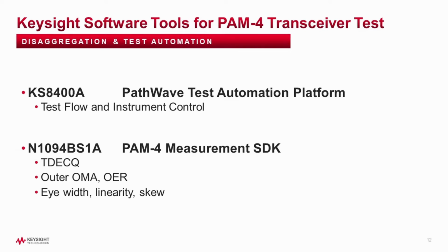For the analysis, we were using the new N1094BS1A PAM4 measurement SDK, which runs on the 4 additional physical or virtual machines. The N1094BS1A calculates key PAM4 parameters like TDECQ, outer OMA, optical extinction ratio, eye width, linearity, and skew.